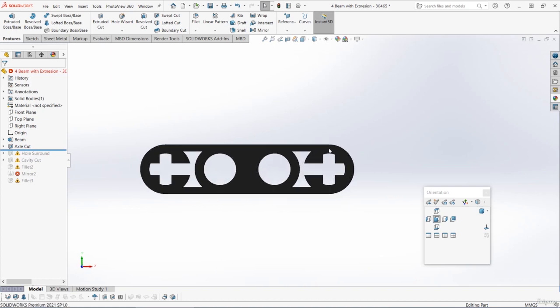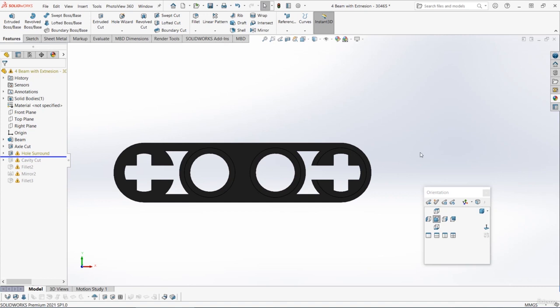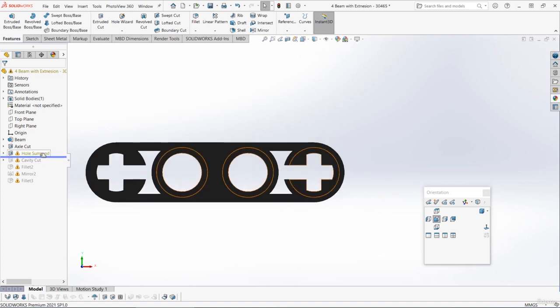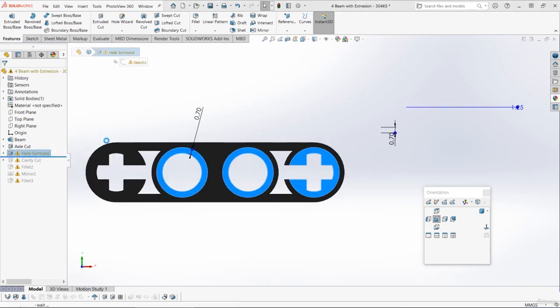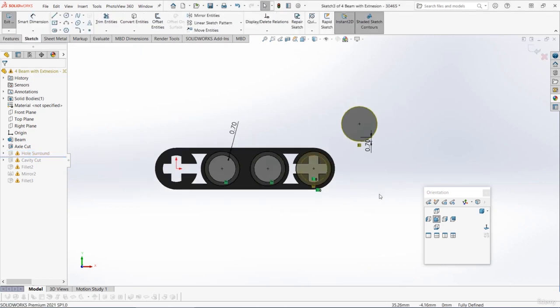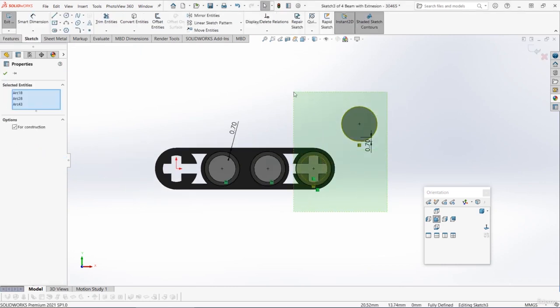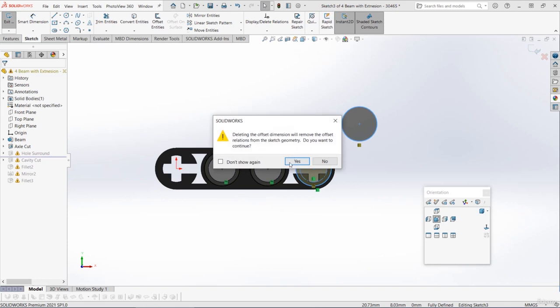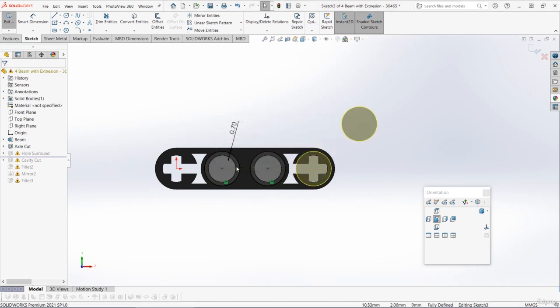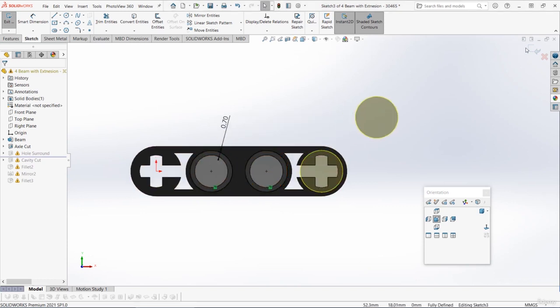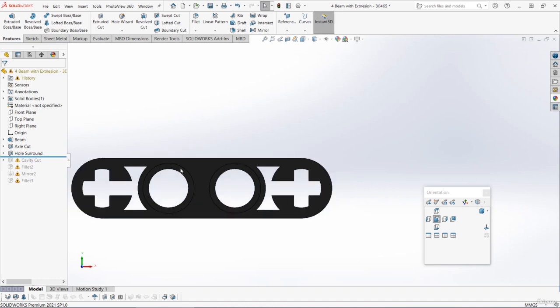Next up, we want the whole surround. Let's drag down below that feature. And again, we've got a warning on the sketch because we've lost some relations there somewhere. So let's edit the sketch underneath the feature and just delete all those extra entities that we don't need. So we only really need 2 circles in the middle for those 2 central holes. Then press OK, and that whole surround should be created.